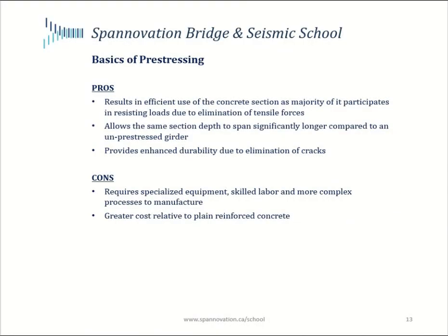So we've gone through some of the basics of pre-stressing, and now it's time to end this chapter with a quick pros and cons statement. So one of the big pros for me with regard to pre-stressing is the elimination of tensile forces in concrete and keeping the section generally under compression. And of course, we've seen that it does that by the application of pre-compression through the tendons.